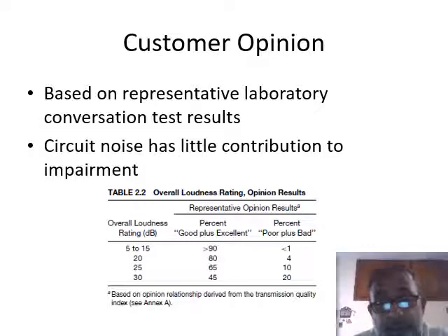In this table you can see that if the overall loudness rating is between 5 to 15, then more than 90% of the customers would say that the quality of the voice is good or excellent, and only just over 1% would say that the quality is bad.